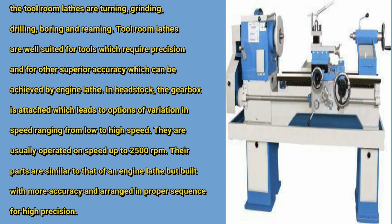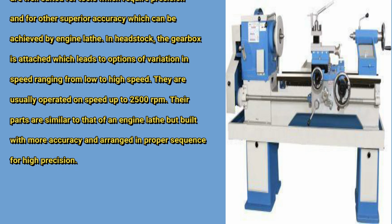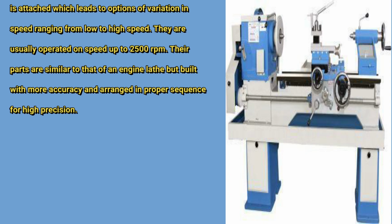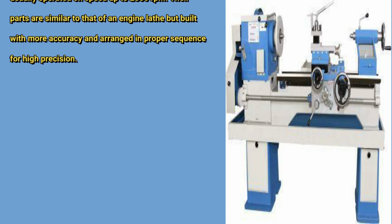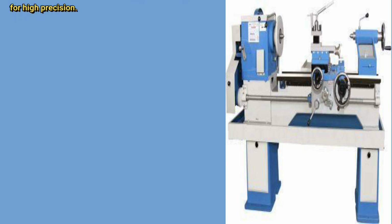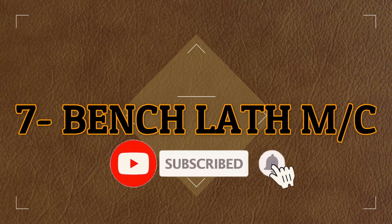In the headstock, a gearbox is attached which leads to options of variation in speed ranging from low to high speed. They are usually operated at speeds up to 2500 RPM. Their parts are similar to that of an engine lathe but built with more accuracy and arranged in proper sequence for high precision.